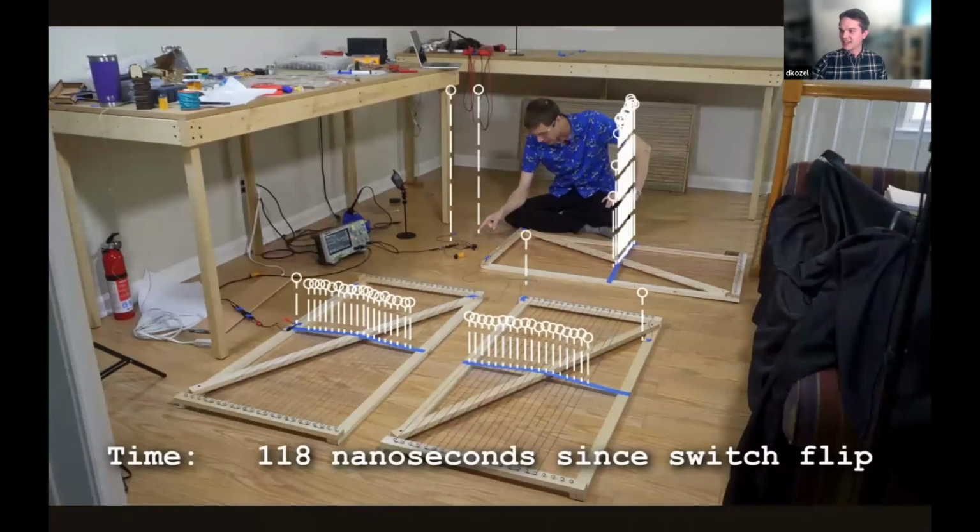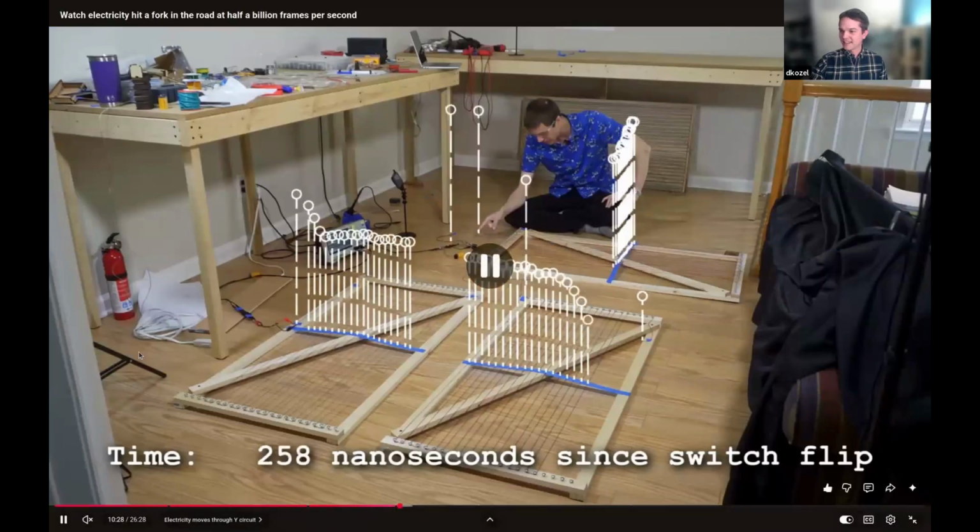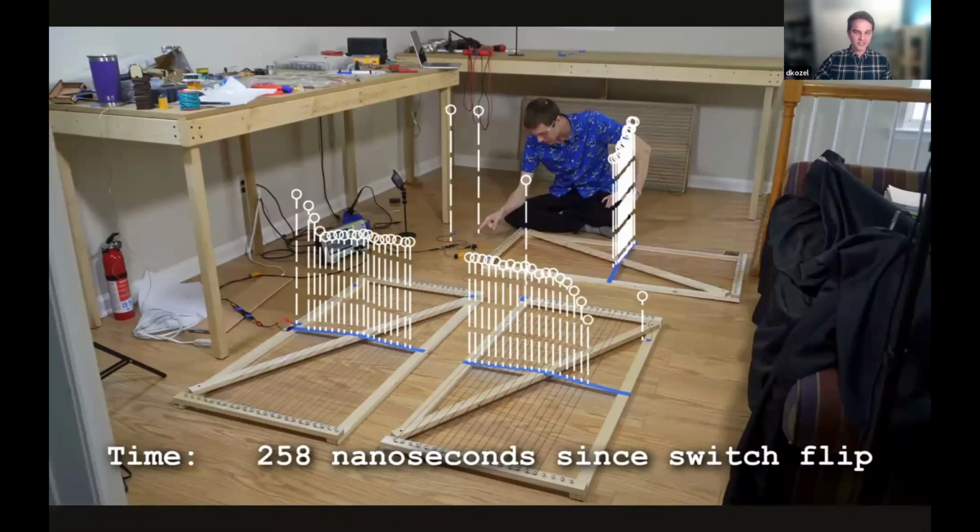He turns it on, and you can see this great animation of the voltage rising as the signal goes out. We can see that the time scale here is 250 nanoseconds, so an extremely short time. This is the concept of propagation delay. If we think of light moving through air, we have the speed of light in air. This is the speed of electrons, the speed of voltage moving down the line, moving down the copper conductor in this twisted pair medium. It's taken approximately 250 nanoseconds to go through this many meters of wire.